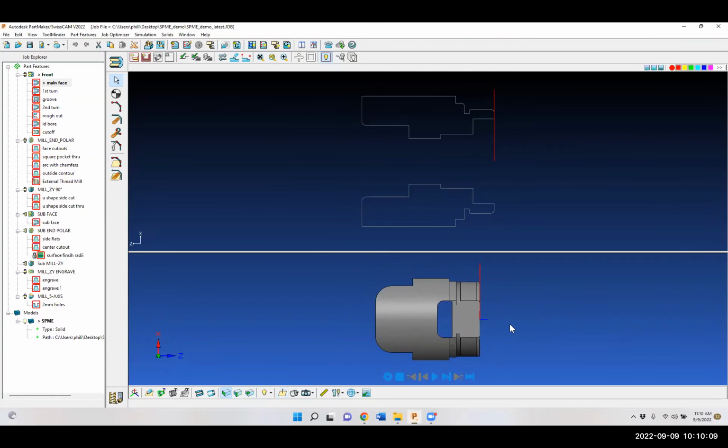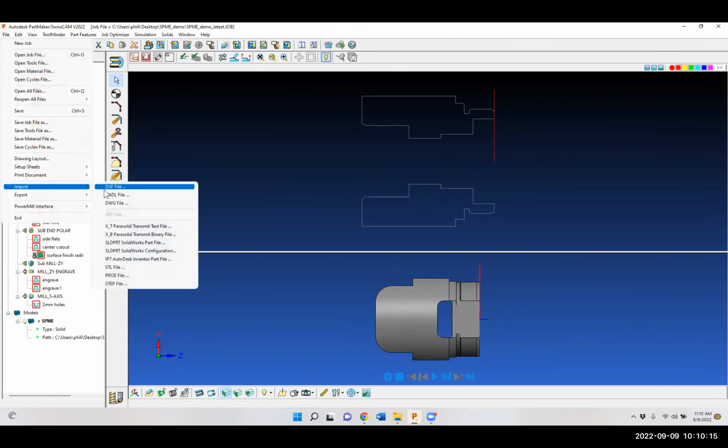So the first thing you're going to need to do is to import the solid model, and we have a lot of import capability. On the wireframe side, we can import the DXF, we can import old CADL or CADKEY files, the DWG drawings from any AutoCAD system. On the solid end, we do the neutral file languages of X_T and X_B.